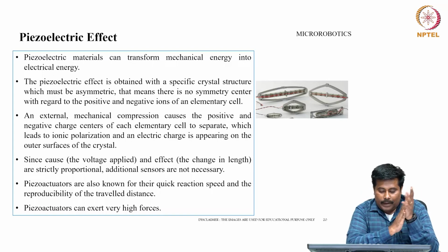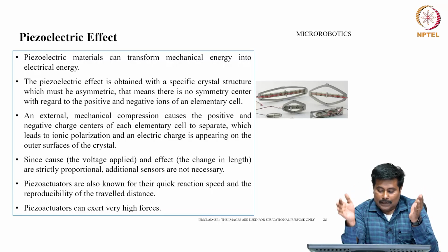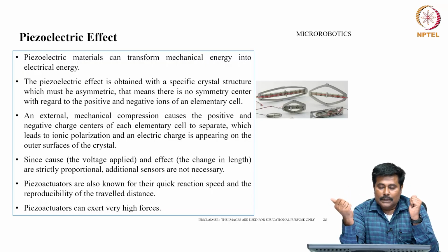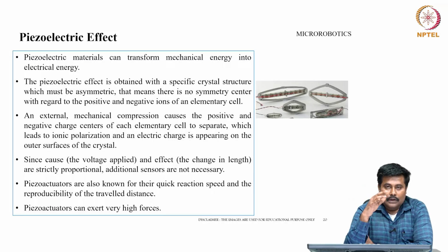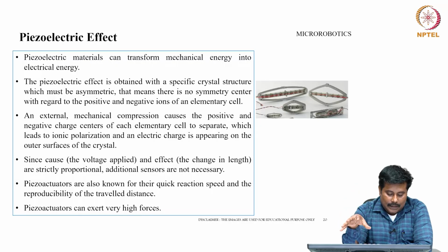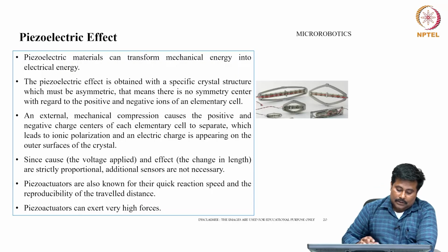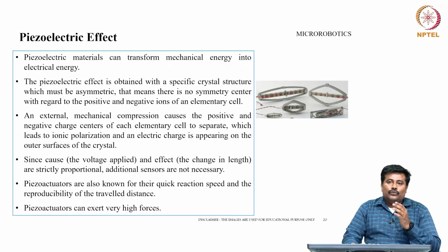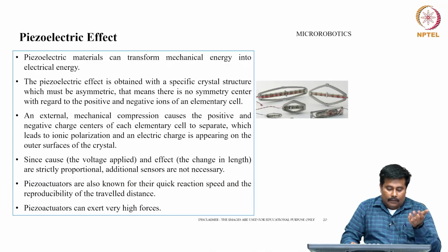An external mechanical compression causes the positive and negative charge center of each elementary cell to separate, which leads to ionic polarization, and an electric charge appears on the outer surface of the crystal. Since the voltage applied and the change in length are strictly proportional, additional sensors are not necessary. And piezo actuators are also known for a quick reaction speed, basically what we have termed a stimulus, and they have reproducibility of the traveled distance.